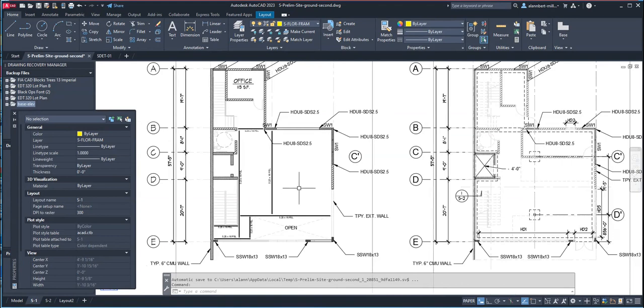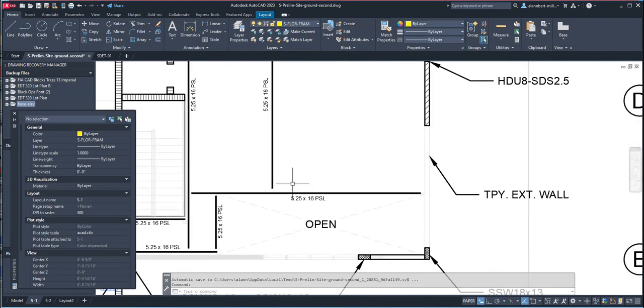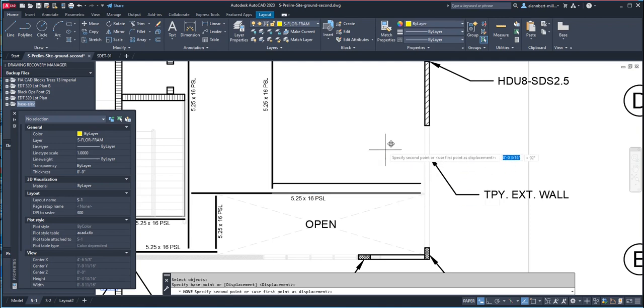We can do them individually. So we can do a P line, and I'm going to just hold this back. Actually, I'm going to copy it from here all the way to perpendicular to here, so it's on top of there. You can't see it's on top. And I'm going to move my last, move L, enter, click anywhere, and then drag up, making sure it's straight up. And then we're going to space them. I'm going to turn on my ortho, it's just straight up. And we're going to space them 12 inches. So we're going to put 12, enter. Okay, now where is it?